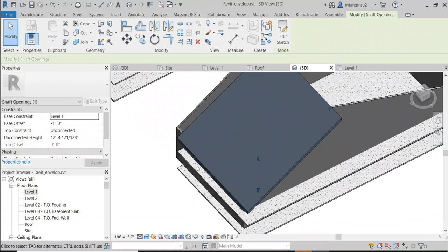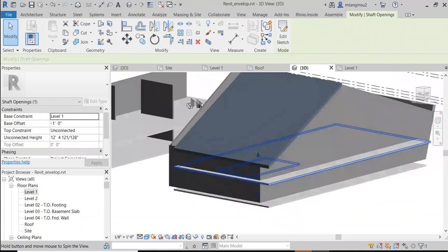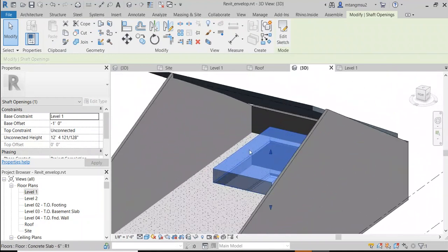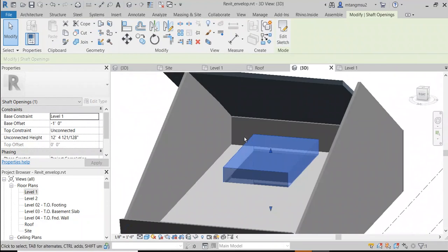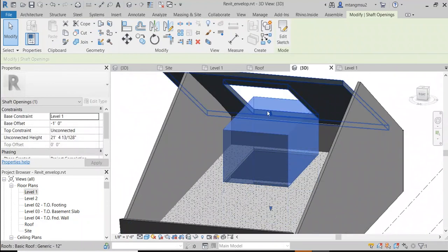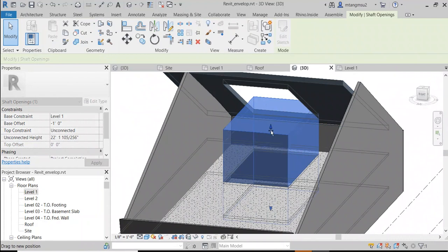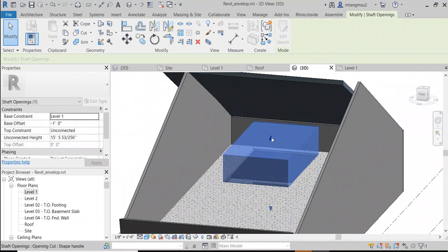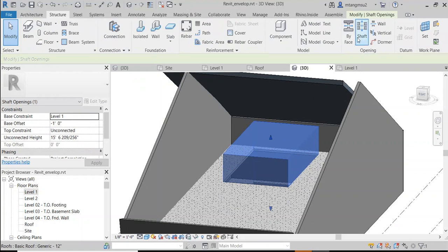Right. So if I drag the shaft lower, you can see the shaft will cut through the floor, right? But it's not going to cut through your roof. So it's really flexible. I know some of you probably have a concrete core for your skyscraper, right? For the tower. So you could actually just easily punch openings through all the levels using the shaft, okay? Which is under here by a shaft.